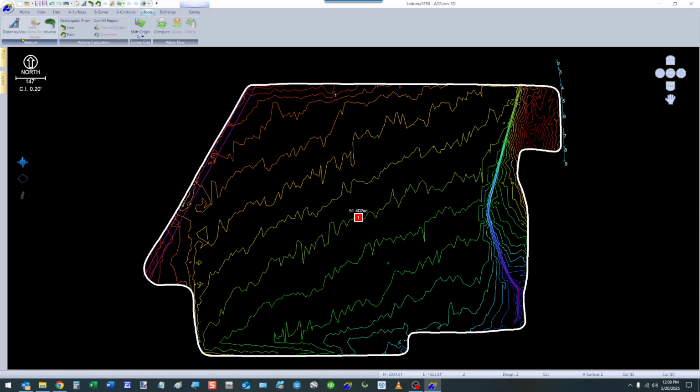You have your tools. Distance area, this is for measuring. If you do just a one click and then move it, you'll notice that it gives you the length, the azimuth reading, and also the existing slope. So from point A to point B right now, there's a downhill slope of a negative 0.05%, half a tenth fall per 100 feet. Once you click, that goes away, and now it's giving you the existing slope from this point down to the next one. And you've got a different azimuth.